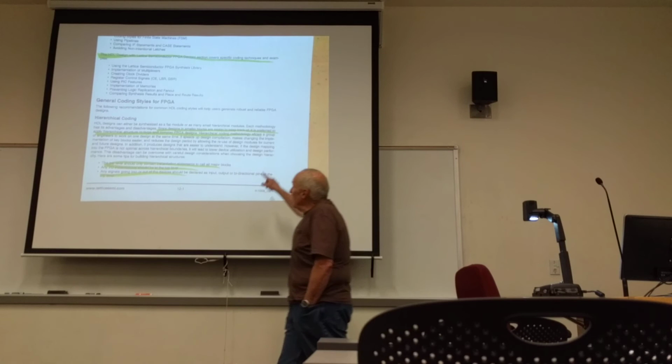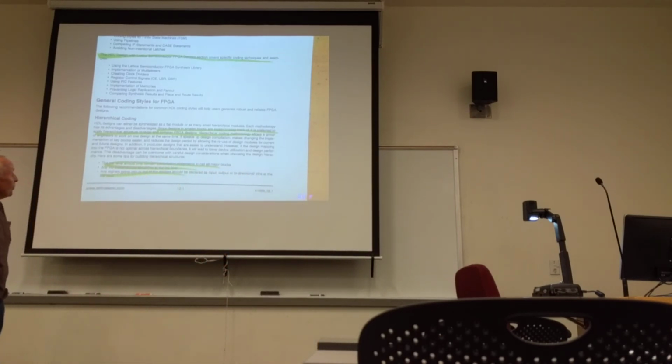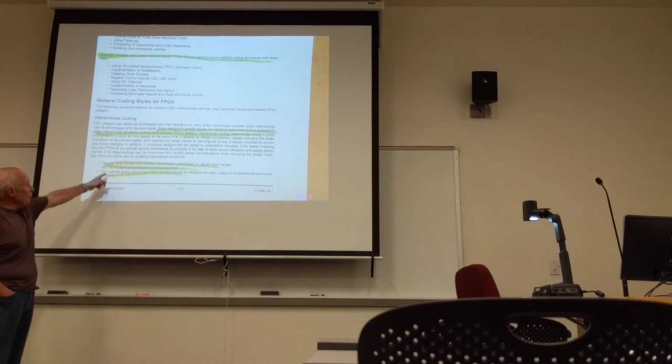Since designs in smaller blocks are easier to keep track of, it is preferred to apply hierarchical structure to large and complex designs rather than having one monolithic module. We talked about constructing the design hierarchy when we were talking about managing complexity. The top module should only contain instantiation statements.